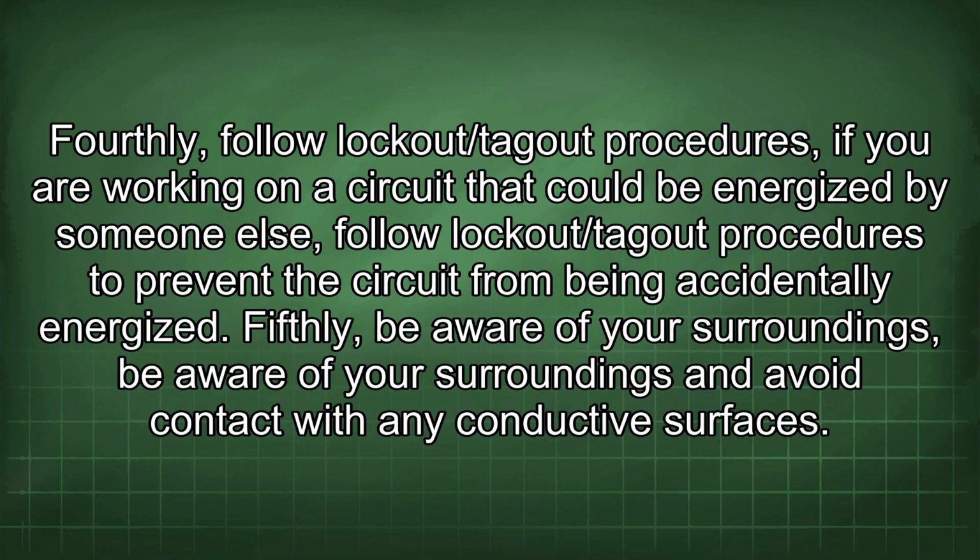Fourthly, follow lockout/tagout procedures. If you are working on a circuit that could be energized by someone else, follow lockout/tagout procedures to prevent the circuit from being accidentally energized. Fifthly, be aware of your surroundings. Be aware of your surroundings and avoid contact with any conductive surfaces.